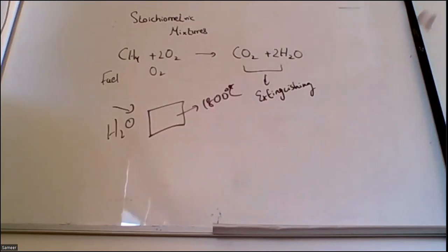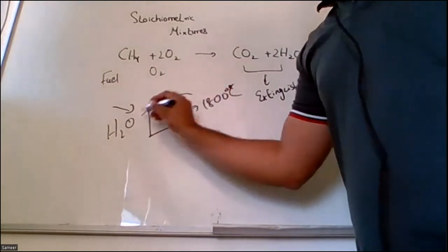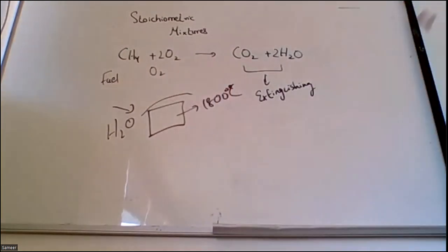So when you apply water on metal fires, the molecules of the reactive metals break down. Hydrogen, as a lone agent, is always going to exothermically increase the reaction. The temperature of the fire is going to rise, and oxygen is going to be an oxidizer. So water is a very wrong agent for metal fires. What I want is a system in which I can first of all cool down the metal, and secondly, the material should have the capability to absorb that much heat without breaking its molecules.